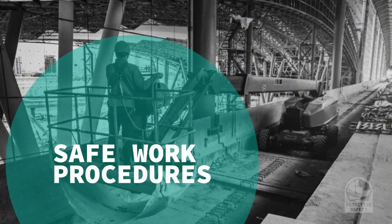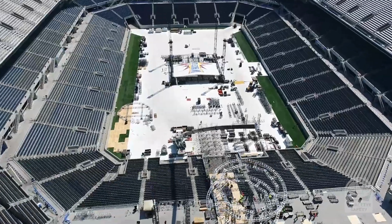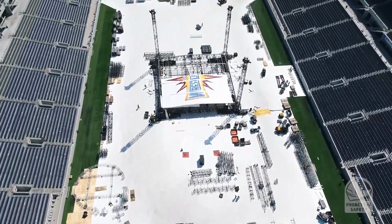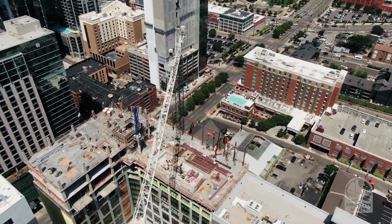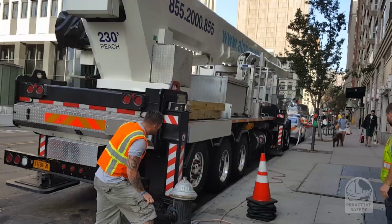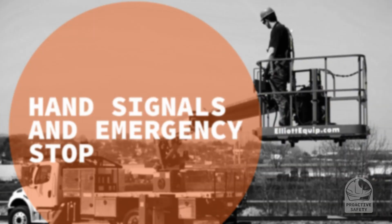Safe work procedures. Knowing your workplace and its risks is highly important, and it can be one of the easiest ways to prevent an accident or an incident. Carry out a risk assessment before the operation is done. Implement control measures to mitigate risks, set up your job site, consider pedestrian safety, and promote communication and safety awareness within the workplace.